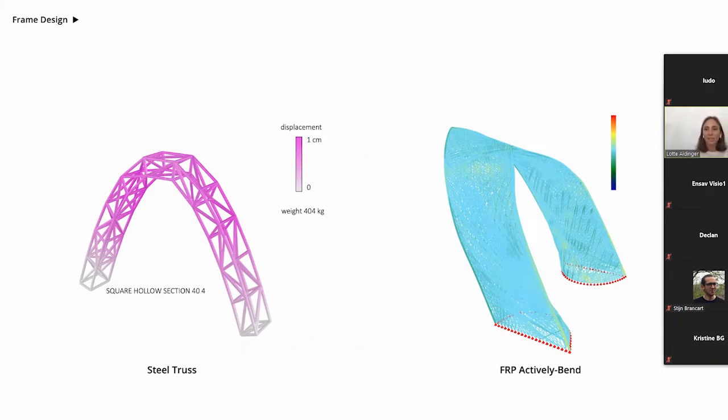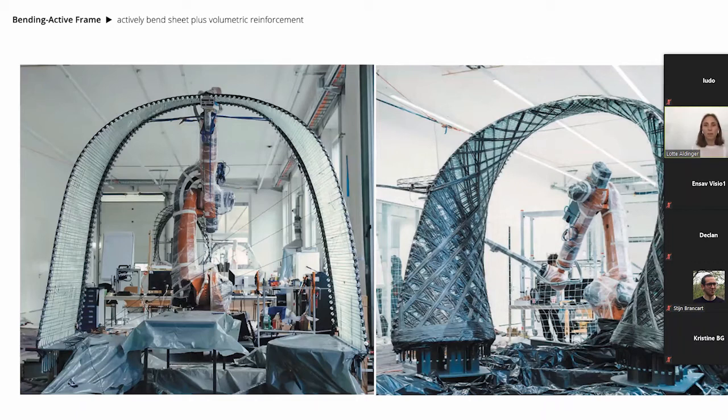And the main aspect I want to highlight here is basically this reinforcement strategy and the fiber directionality, because the initial flat FRP plate that you see on the left is really wobbly, so that it can be bent into the shape. Of course, we also have to pay attention to the fiber layout so that it can nicely bend.